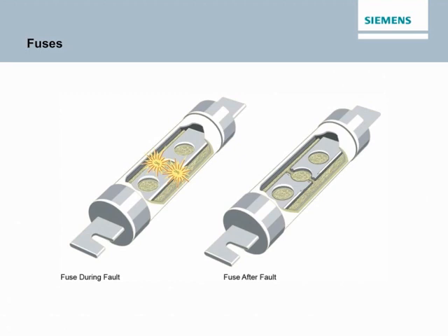A fuse is a one-shot device. The heat produced by overcurrent causes the current carrying element to melt open, disconnecting the load from the source voltage. Fuses without time delay provide excellent short circuit protection. When an overcurrent situation occurs, heat builds up rapidly in the fuse. Fuses without time delay usually hold 500% of their rating for approximately 1/4 second, after which the current carrying element melts. This means that these fuses cannot be used in motor circuits, which often have inrush currents of greater than 500% while the motor is starting.